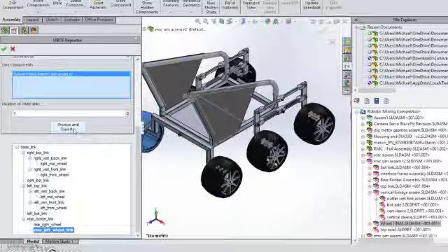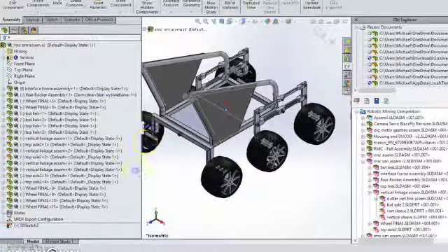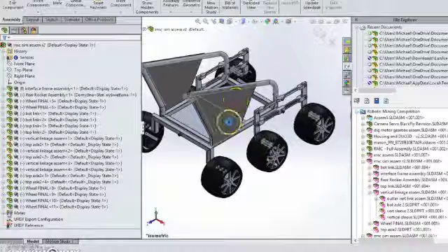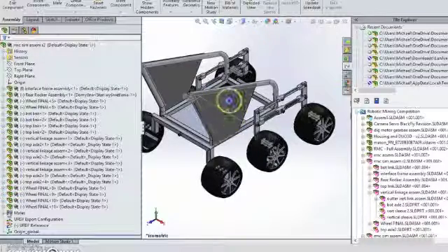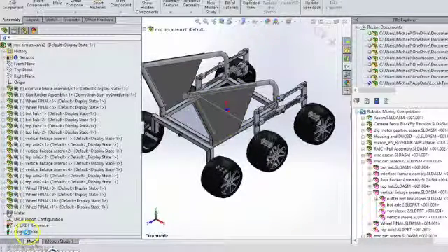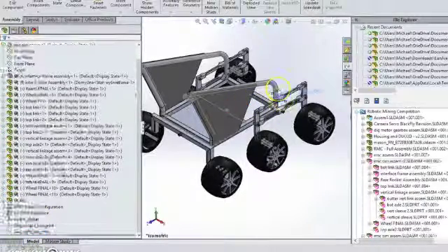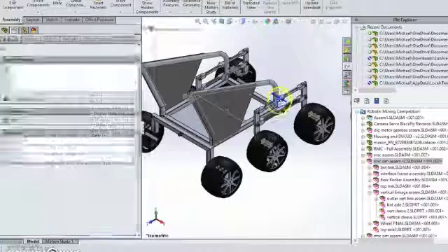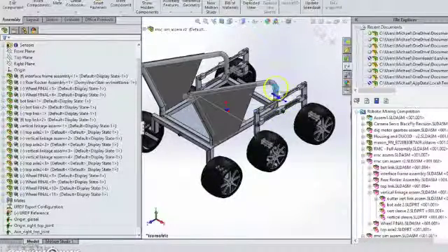So this is going to create the URDF model. We can see it creating the origin at our origin. That's the global origin, and it's creating this URDF reference. So now we see that it's correctly found the origin and axis for this top link joint.